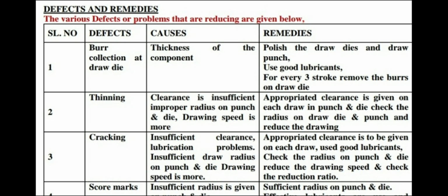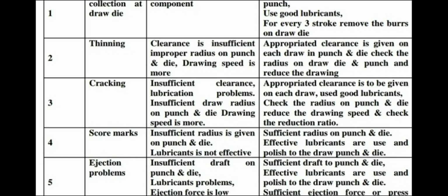Then cracking. So insufficient clearance due to lubrication problem, or due to insufficient draw radius on punch and die, or drawing speed is more. The score marks, some marks are there.